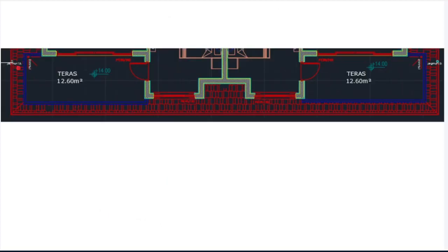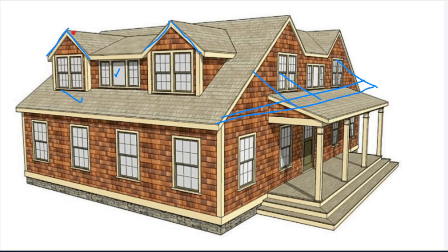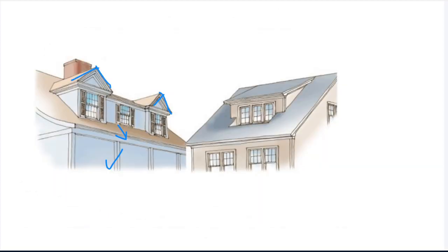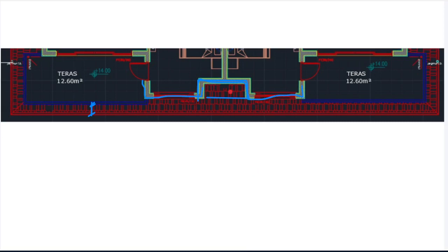Yes, here again, at least 30 centimeter, you can see in the roof plan. Even creating a dormer, this is a dormer, and you are going to have a setback. So the reason that we could have this one from here, but the reason that we are going to have a setback is to create a nice view of those, let's say, gables. That is why we are taking this 1 meter inside. This setback. So that's why we are asking you to put that setback.